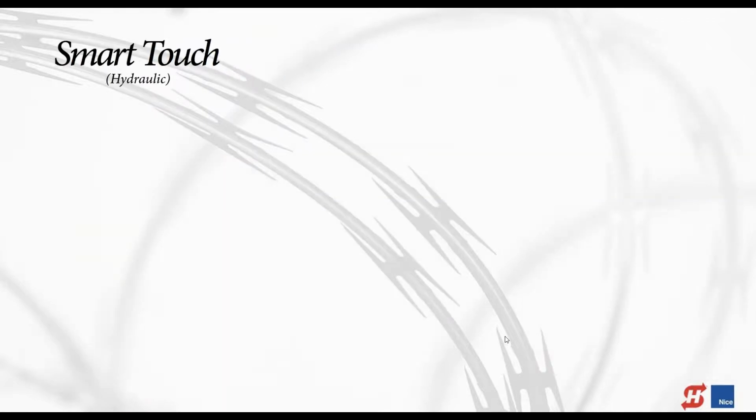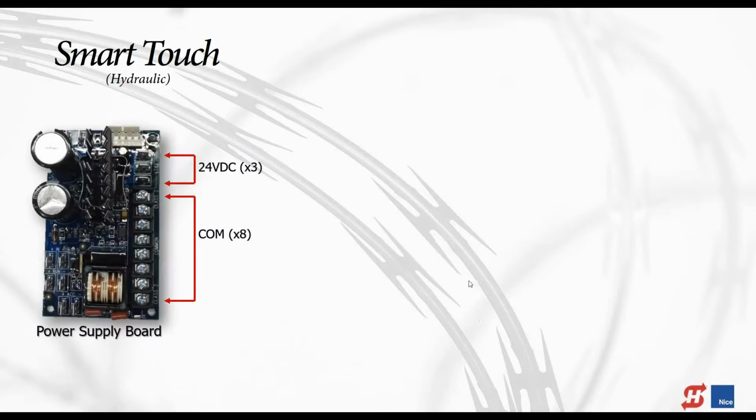Let's take a closer look at that Smart Touch hydraulic system, okay? So here we go. There's that power supply board. The thing to note on that is we have the 8 COM terminals on the right here. So when you're plugging in your peripherals or your access control devices, usually it's a 2-wire, a COM, and the other end connected to an input of some sort. Here we have the COM terminals that all bus together. Up at the top there are our 3 24-volt DC spade terminals. So a lot of our devices require a 24-volt DC power feed, and that's where you can get them from.